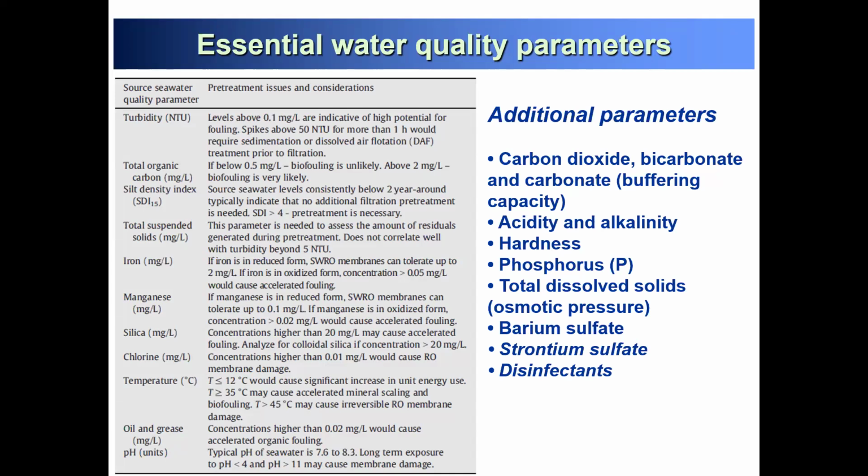So 28, and then 60 bar. You pressurize at 60 bar, 70 bar, and this will create your 50% recovery, because the applied pressure must overcome the osmotic pressure, and 60 bar is almost double 28 bar. So you push your water molecules, and your brine, your concentrate, becomes double as well.